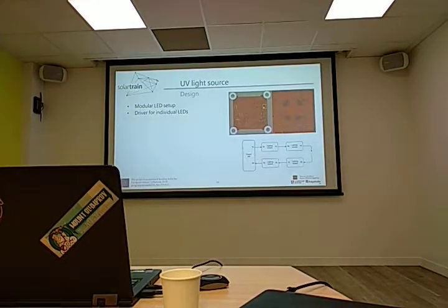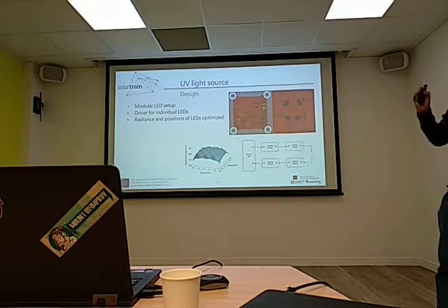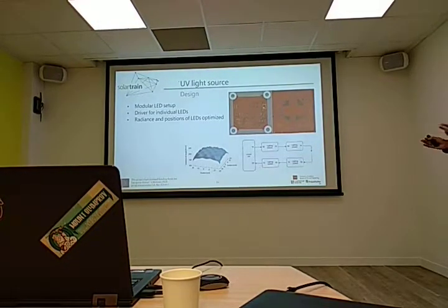A master student at the University of Jülich designed some drivers for these LEDs, which could be controlled in a daisy chain operation, so we could put as many LEDs as we wanted in a chain and then build an array of these LEDs. And we did our own calculations: if we drive all LEDs at 100% of the power, we get quite a non-uniform irradiance, so we also have to dim the central LEDs to get a nice homogeneity of the radiation.